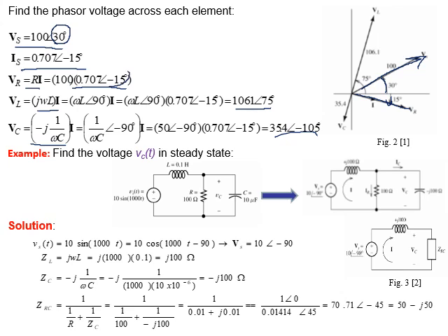You see here the angle is minus 15, which is the voltage of the resistance in phase with the current, which is what we discussed before. They are in phase. But have a look at the inductance. The angle is 75 in the positive direction, so from here to here is 75. Just a minute. I remember from the previous week's discussion, we mentioned that for inductance, the phase shift between current and voltage should be 90. Yes, correct. This 75 plus this 15, altogether 90. This is the current and this is the voltage.